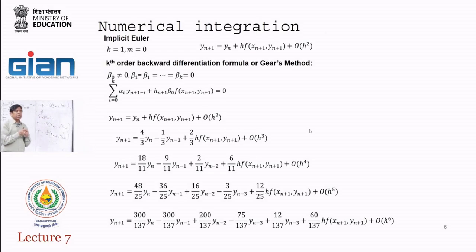It will start with that maximum order, which gives you the highest accuracy. If it cannot solve it, it will keep cutting. It will say, I started with the 5th order and could not converge, then it goes to the 4th order. It could not converge, it goes to the 3rd order, then the 2nd order, and it keeps going. This gives you a lot of flexibility in solving the system of equations.